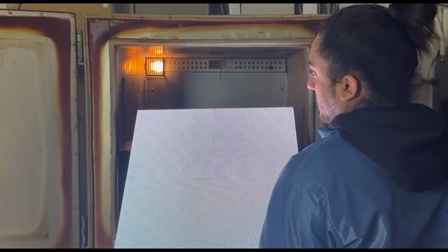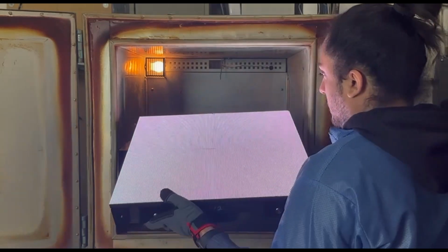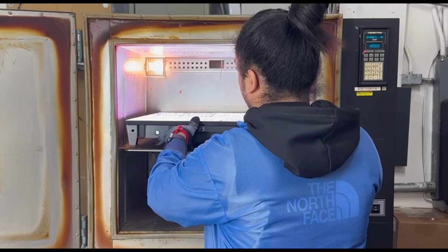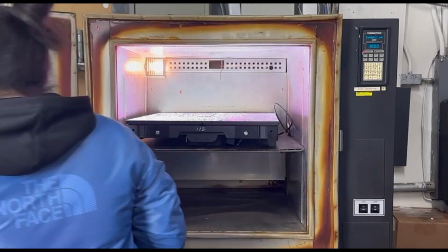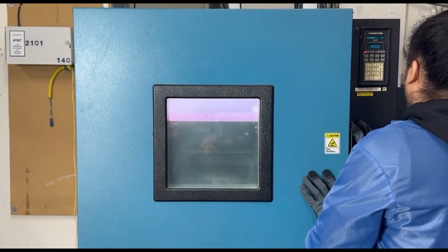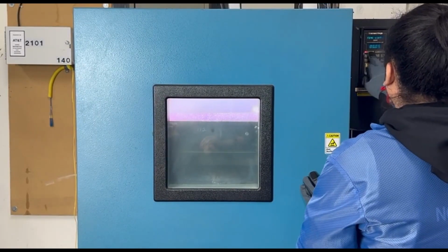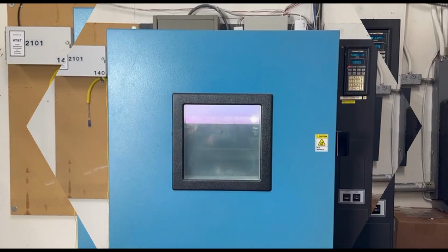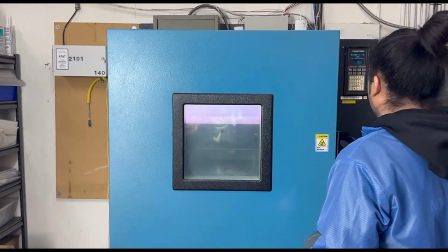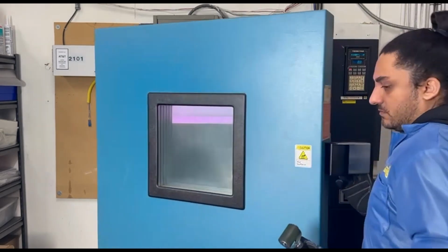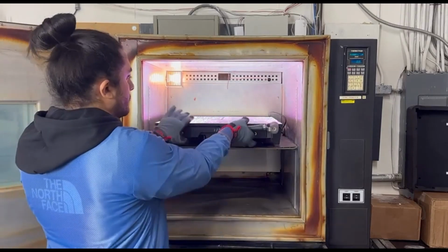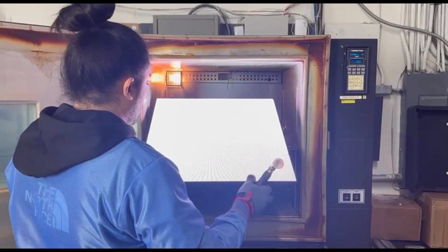The third test that we want to discuss is the thermal test. For thermal testing, we use Thermotron's S8 environmental test chamber in accordance with the below standards that address thermal durability testing procedures. Thermotron's S8 chambers offer high performance with 227 liters, about 8 cubic feet of workspace for running this test. We evaluated the X2V style in the chamber, exposing it according to the listed standards, and X2V passed the requirements, functioned properly, and remained in excellent condition after all tests.